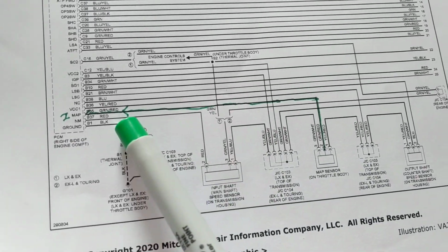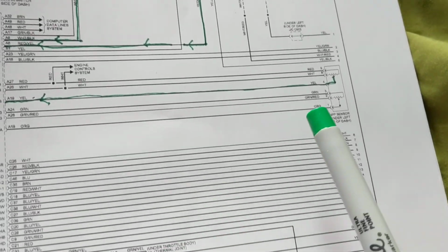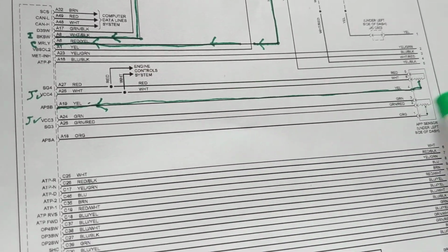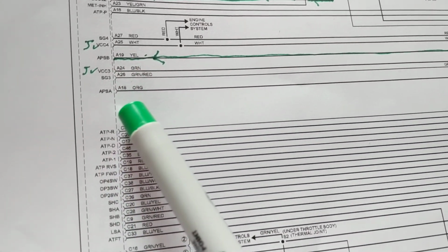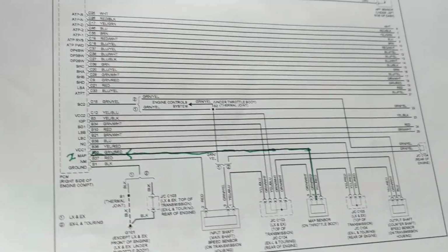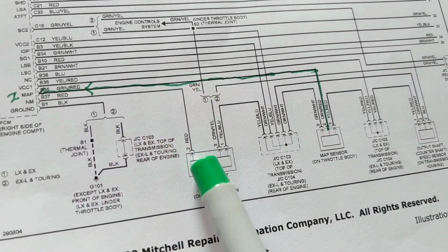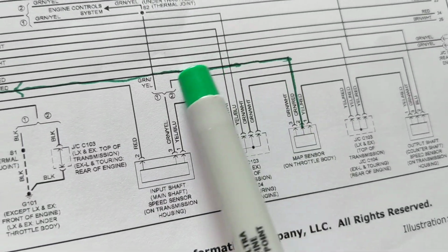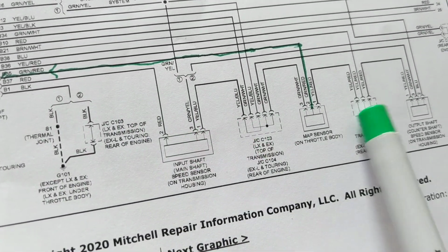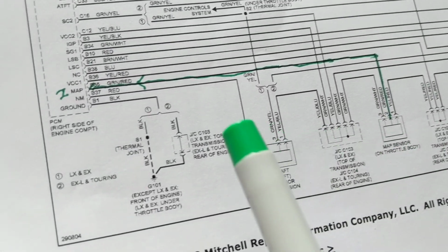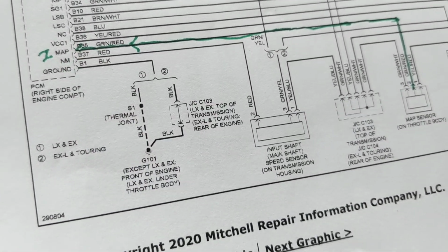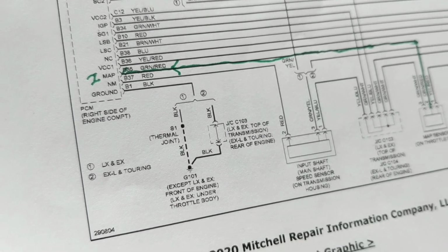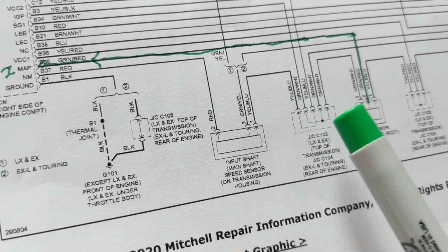You just have to follow the line where it goes. Any sensor, whether it's a mass airflow sensor or an intake air temperature sensor. If you're not sure of the abbreviation, this is my technique: go see where it's connected. Usually the middle one is the signal, giving it back. The other two are a ground and a voltage. VCC is like IG, which is ignition voltage, 12 volts, or in this case, 5 volts.